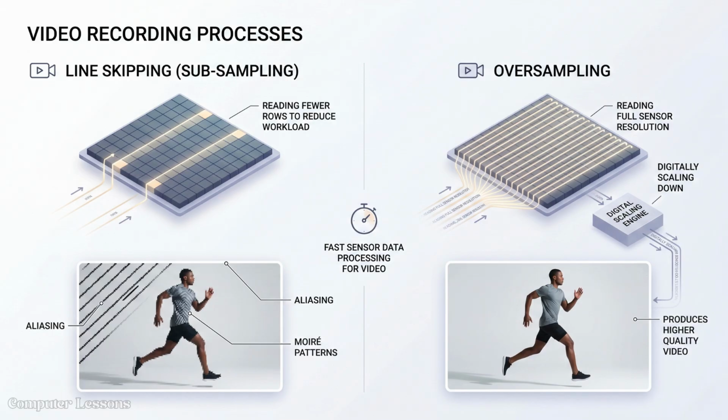Video recording requires the sensor to process data much faster than for still photography tasks. Some sensors use line skipping to reduce the workload, which can cause aliasing and moiré patterns. Higher quality cameras use oversampling, reading the full sensor resolution and then scaling it down digitally.